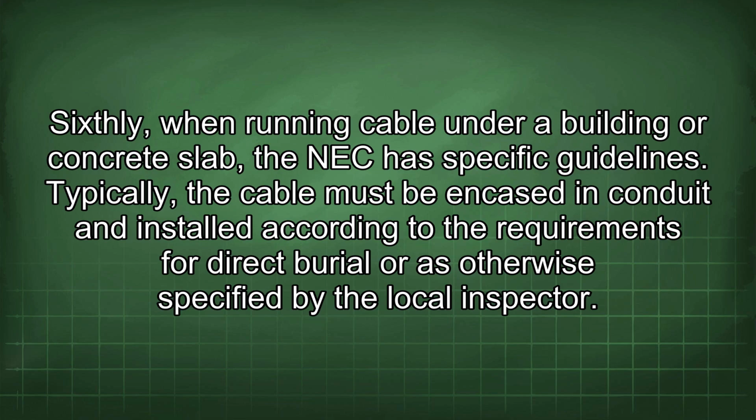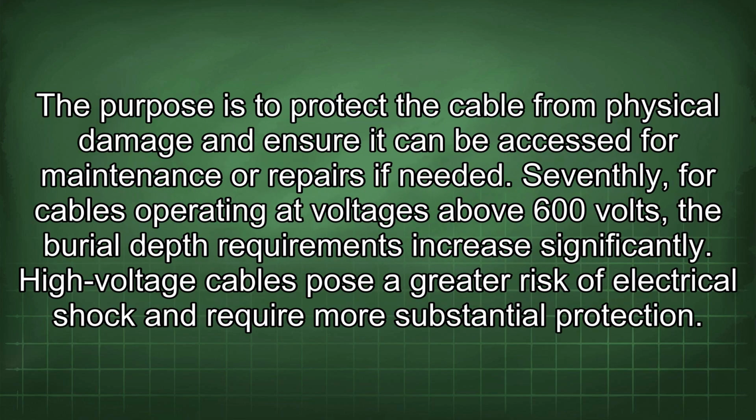Sixthly, when running cable under a building or concrete slab, the NEC has specific guidelines. Typically, the cable must be encased in conduit and installed according to the requirements for direct burial or as otherwise specified by the local inspector. The purpose is to protect the cable from physical damage and ensure it can be accessed for maintenance or repairs